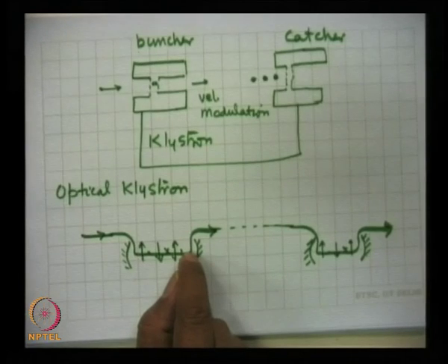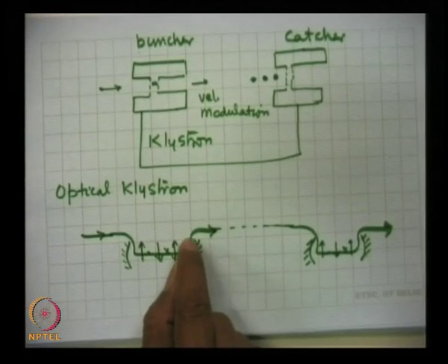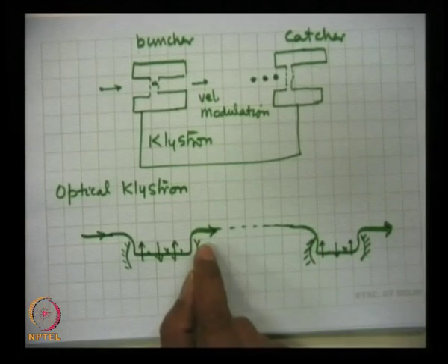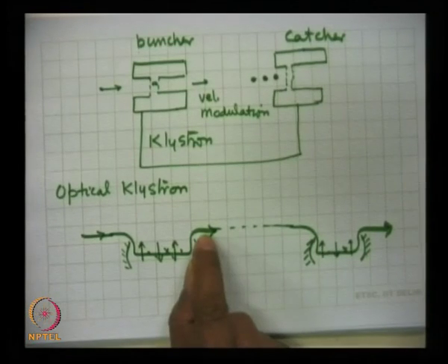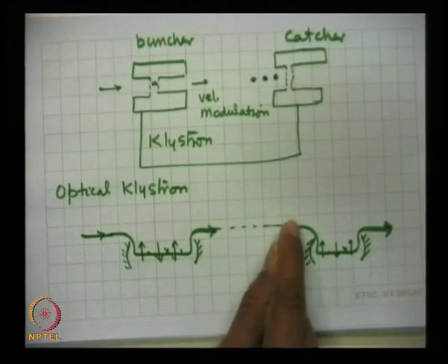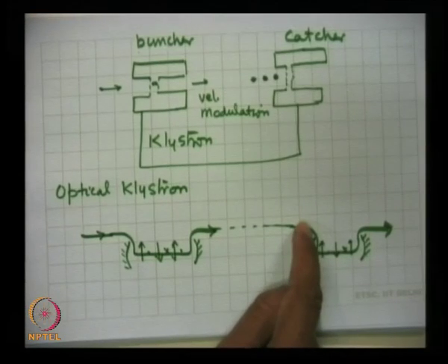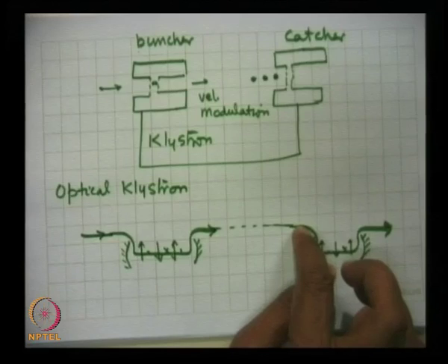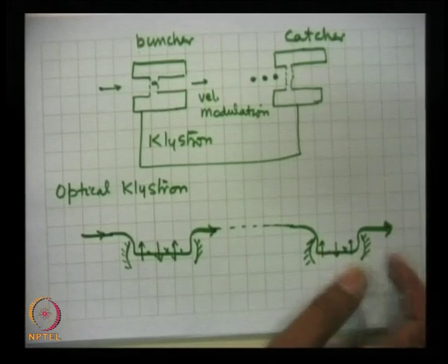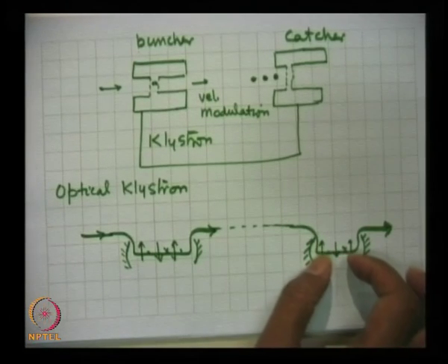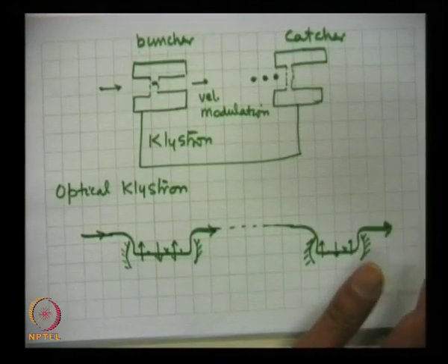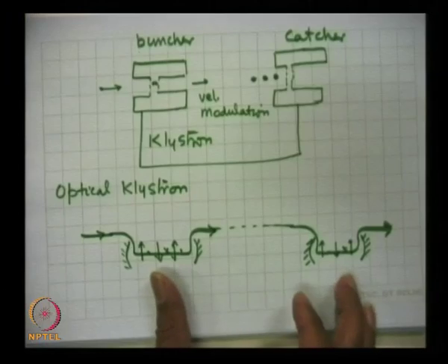Or modulate its velocity. So, when the velocity modulated beam arrives in this space, called the drift space, the electrons which are fast moving will catch up with the slow moving electrons which had left this cavity earlier. So, there is a charge bunching, and those bunches of charge, when they move through the second cavity, will produce much enhanced radiation here, and you can get optical amplification. And this is a very fascinating device.